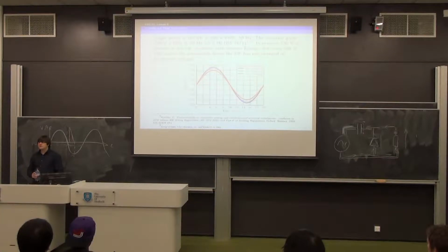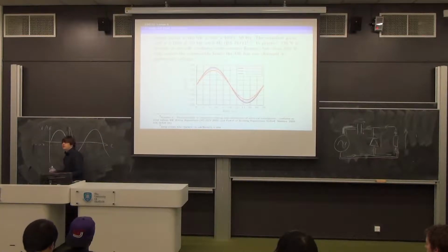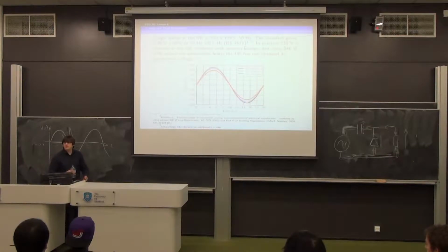Belligerent British? Not that. It's an economic reason. If a power company supplies you with 240, and you've got some light bulb which is notionally 60 watts, it will draw a certain current and you'll get I²R power loss in the bulb. If you supply with 230, or even better, you'll get V squared upon R, makes it more obvious. If you're supplied with 230, your V squared's dropped by 10 squared, which is actually quite a lot.